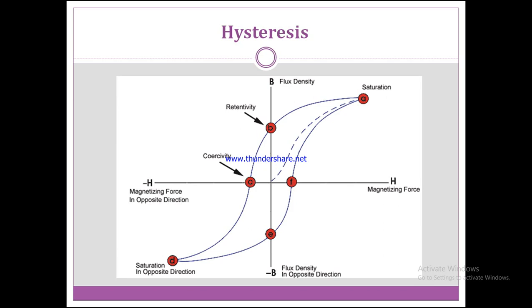The portion of power lost corresponds to the difference between the energy stored and the energy returned by the magnetic core. This is called the hysteresis loss, which mainly depends upon the frequency of magnetization, the area enclosed by the hysteresis loop, and the volume of that material.